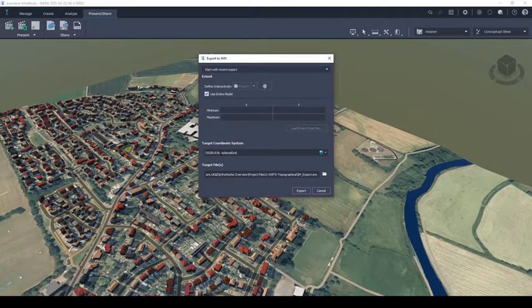We can then select what the target coordinate system will be. I'd recommend using the same coordinate system throughout a project as good practice and to model everything geospatially correct, no matter the application used. This will mitigate against any coordination issues that may arise as the project progresses.